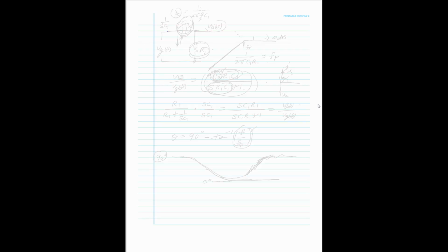So now we're going to consider, well, how do we get a zero out of a passive circuit? So we flip the capacitor and the resistor, and we have this circuit, where the capacitor and resistor are flipped. Now immediately, again, we want intuitive stuff as well as the mathematical stuff. And the intuitive stuff to me is, again, always walk the frequency. At very low frequency, this capacitor reactance is an open circuit because it's 1 over 2 pi f C1. And that's the capacitor reactance.